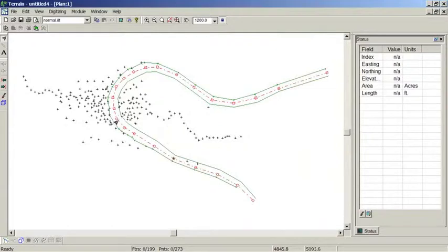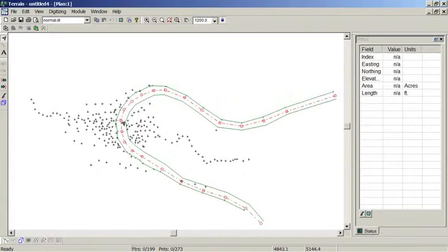There's my road. This is a culvert replacement in this area right here, so I really don't need any data outside of this area. That's why I only have data over here. I'm going to extract the culvert, get some volumes, like I said before, and then I'm going to insert a new culvert and then design a road over top.